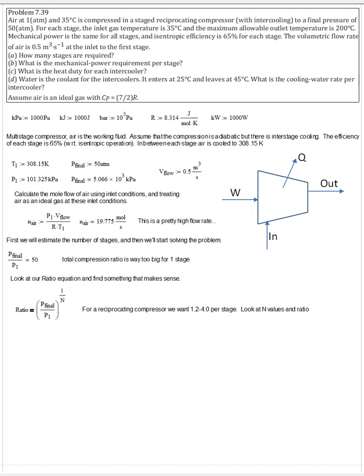What I've done then is take this equation and set up a little series, and you can do this in MathCAD. You set up n as my counting variable, so n equals 1 comma 2 and then colon. If I want to set up a series, n gets 1 comma 2, and that sets my interval. If I want to continue that interval, I just press the colon key, and that gives me my ellipsis. Then my final value I just enter, and I did that as 5.